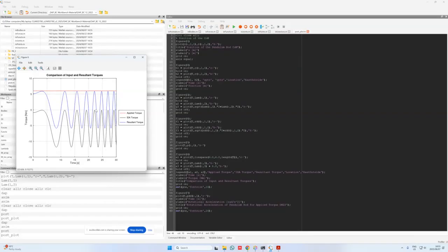In this case, the system says, well, I have a driver function that I need to meet. I need to maintain an angular acceleration of 2 pi over 60 radians per second squared. So in order to achieve this, in light of the torque that is being applied to the system, I need to apply a braking torque so that when the angular acceleration attempts to go above the 2 pi over 60 limit, I can brake it and make sure that it remains at that constant level.